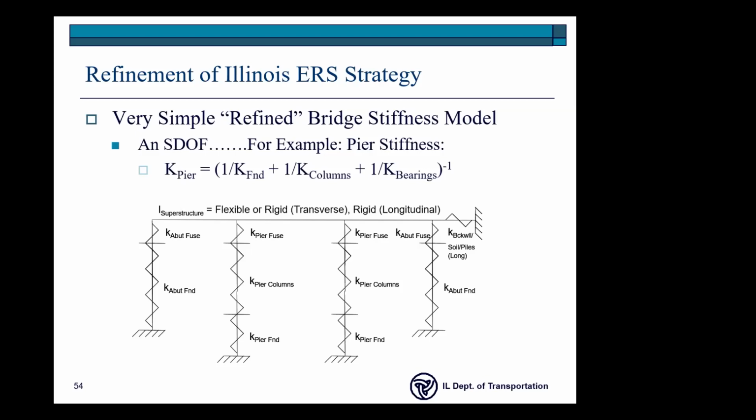Well, I don't think we're very sophisticated in doing that. Okay, how much do you know about, are you well schooled in how to calculate or estimate damping in structures? Yeah, we can calculate based on the hysteretic loop of the column during an earthquake and how much is the area within the loop.